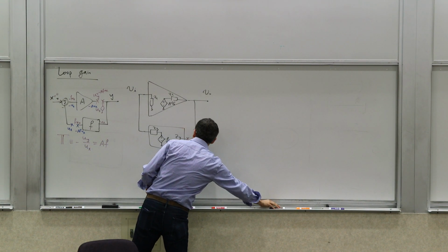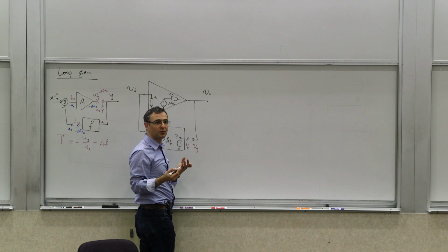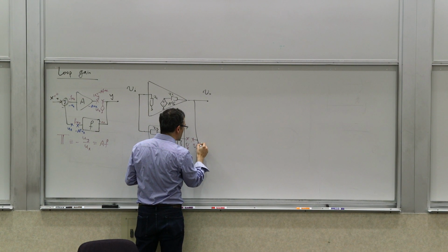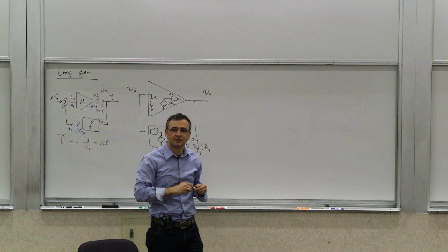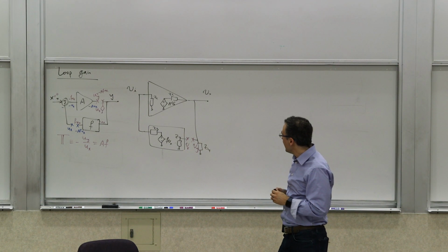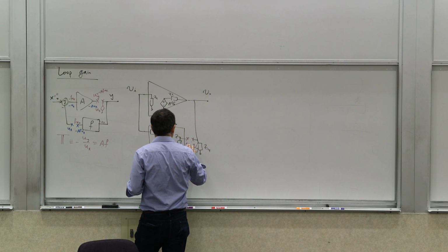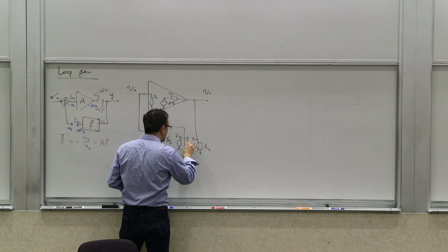Does it make sense to say, look, this guy was loading this. So if I want to see what voltage it would have induced, I should probably put this Z4 here, right? And see what it does with that Z4. And then I say, OK, my Vx is really a voltage source. You can think about it as Vx.